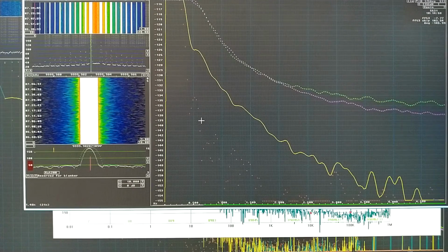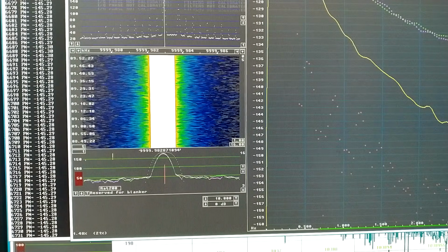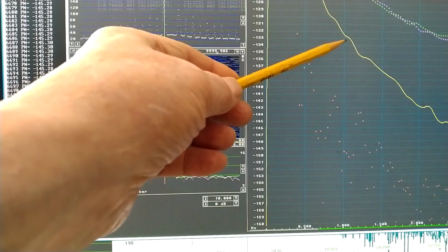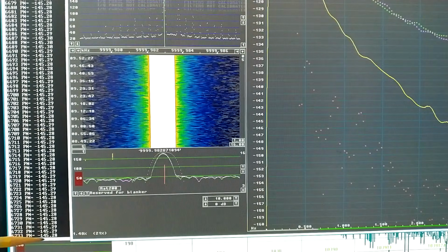With the experience of temperature cycling crystals in another oscillator earlier in this video, I decided this is an aging problem, probably, so I switched the supply voltage on and off for a couple of times, maybe 10 times, and then started again, and the performance was clearly and significantly better than before. Well, 133 was a bit optimistic. It is more like 132.5. But I could see clearly an improvement here on the average noise.